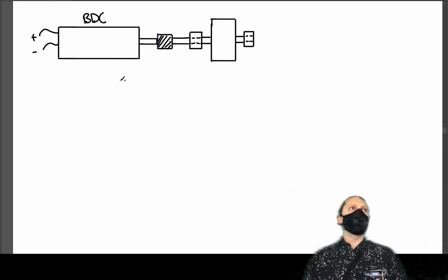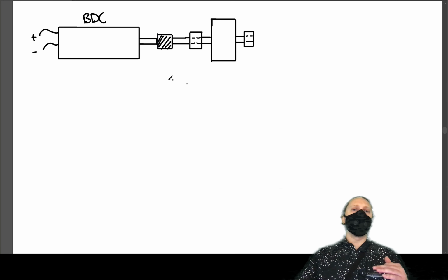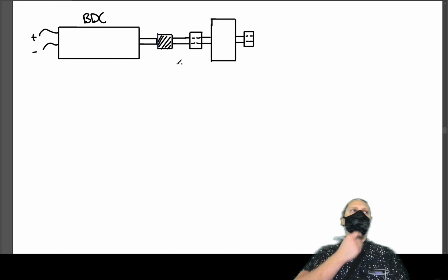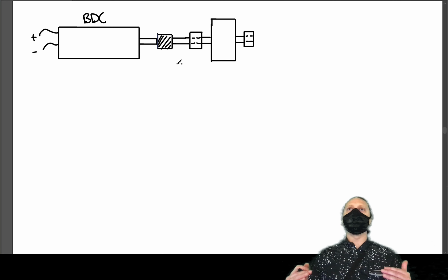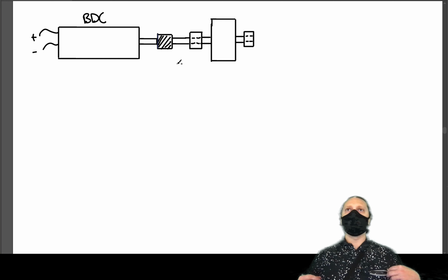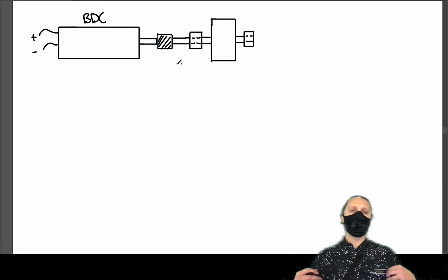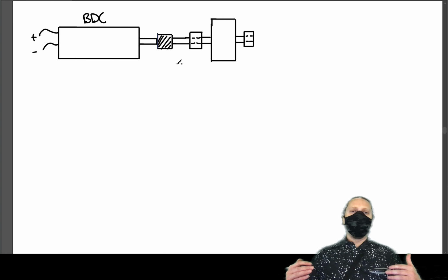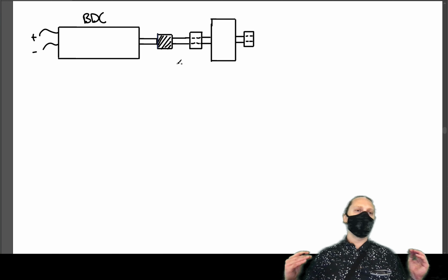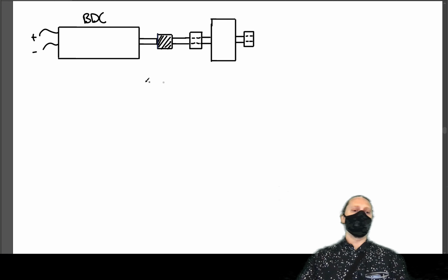But it has to do that in a way that's pretty special because these two shafts are never perfectly aligned. If you spent any time trying to build stuff in a machine shop, you know that nothing is ever perfect. It's only as close as the tolerance tells you it's going to be. So it's very challenging to get two shafts to meet up perfectly parallel and not offset at all.